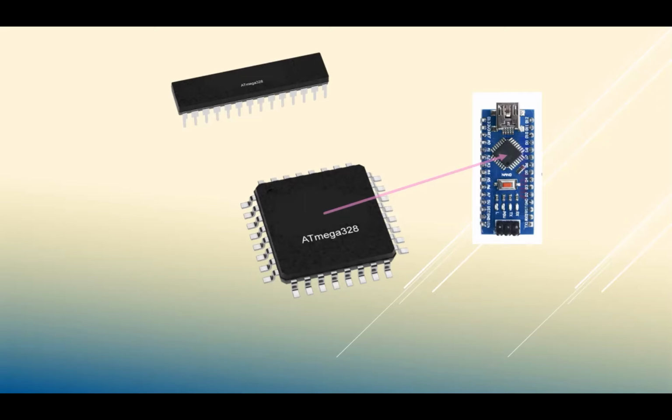So the Arduino Nano isn't some special thing. It's just a board that happens to have an Atmega microcontroller on it with add-ons. It's got a voltage regulator, LEDs, and connections for programming it. You'll see the USB socket, for example, up there. So it's got add-ons, and all the pins are taken out conveniently. You're not trying to solder onto these horrible little tags on the side of a surface mount. It makes it convenient for users. So that's all we're talking about. They're based on Atmega 328s, which I'll look at a bit later.